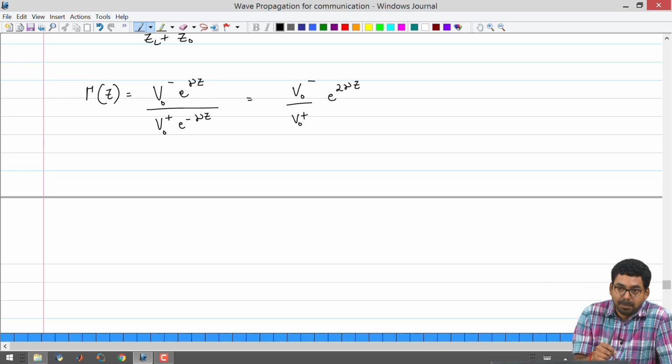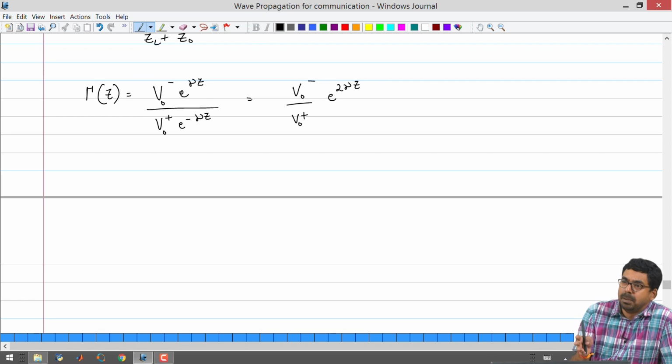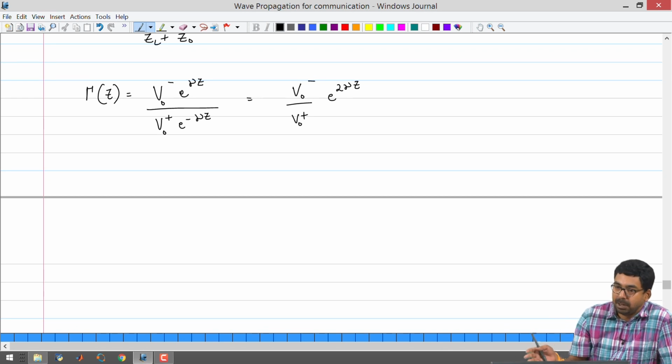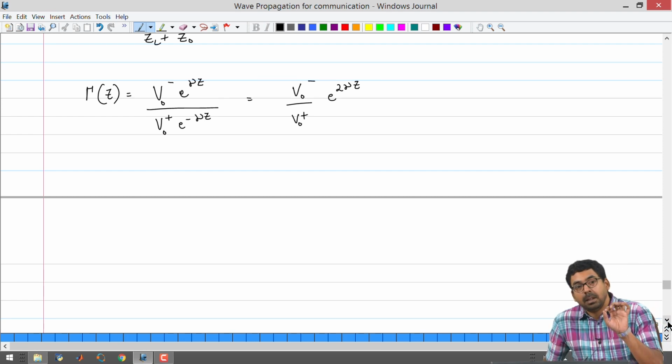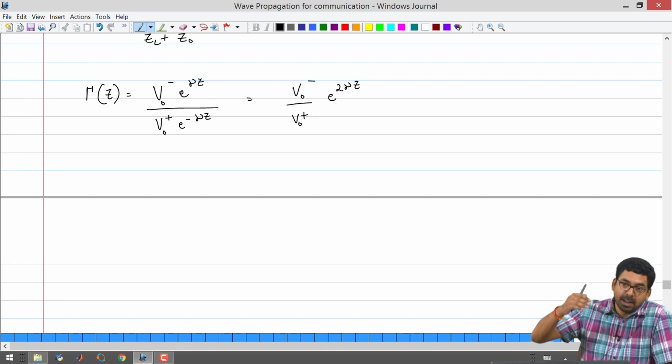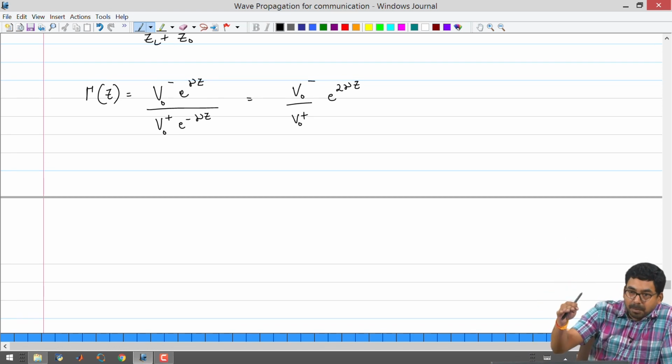So, if you go back to your simulations and use a sinusoid, you say open circuit or a short circuit boundary condition, you will be able to see some standing wave patterns. There will be some nodes, some places which are anti-nodes, and you will be able to see what is happening. So, this means that at certain places the voltage is always pegged at 0, okay. Now, let us look at the other place where it is going between a maximum and some minimum, alright.